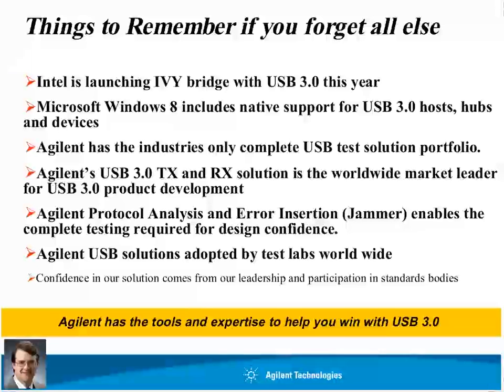So we're really limiting the amount of time we can look at with a scope protocol analysis capture. The difference is how much time we can capture. For USB 3, at the typical sample rate we use for the protocol analysis tool, we're looking at maybe 2 seconds maximum of bus protocol activity.